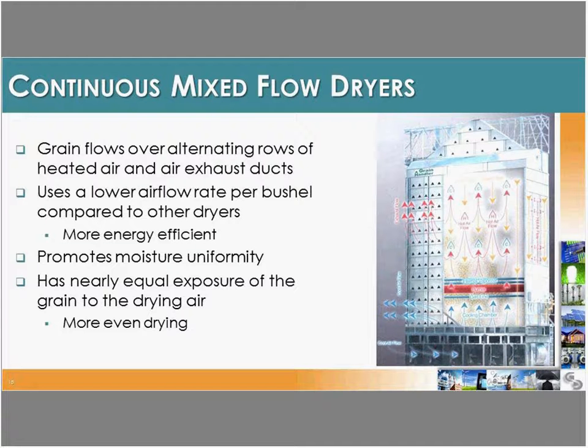They say it uses a lower airflow rate per bushel compared to the other dryers, and that's where they're saying it would be more efficient. And it does promote more uniformity of the moisture content because that grain has a near equal exposure to the drying air. So they say it gets that more even drying. And as it comes down and is dried and cooled, it is then moved to another bin.